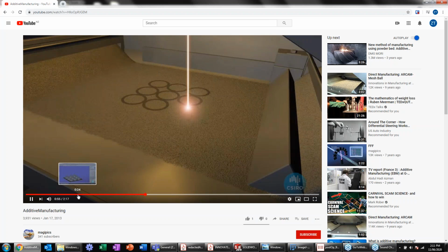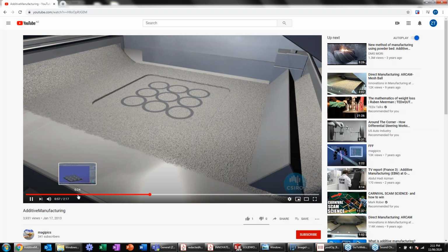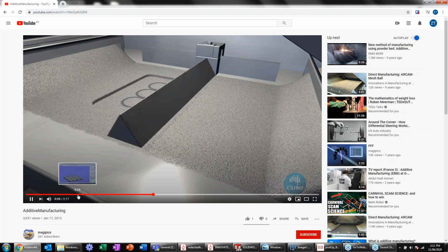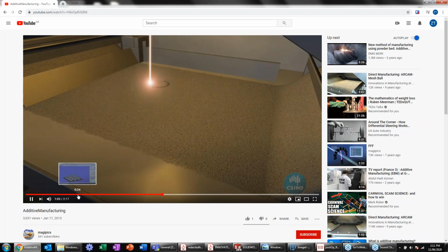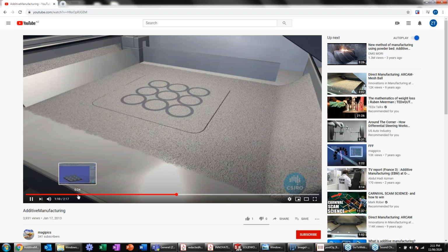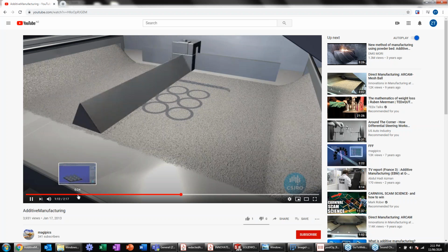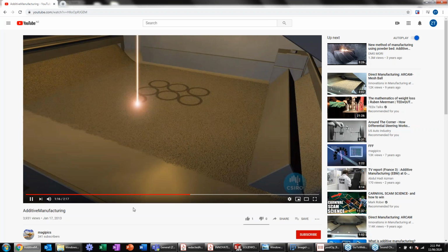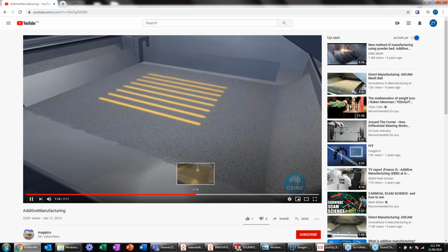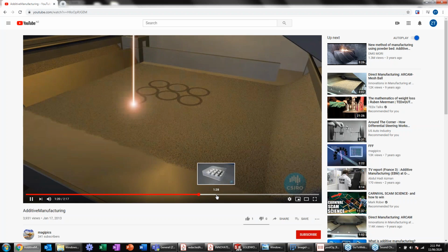So this is a bit of a unique process in the fact that we sinter the powder before we mount the parts. Because we heat layer by layer, at the end of the build, we get a fully annealed part out the other end. But that also means that you've got a whole bunch of sintered powder surrounding your parts now. So we'll see in this animation, this keeps repeating, layer after layer after layer.